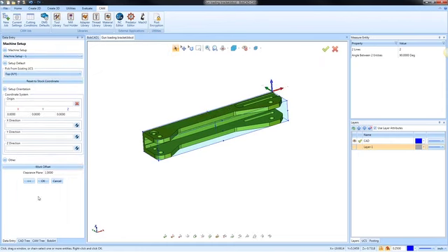Really, our next step here is to set our 0 position, okay, or our origin, as we call it: coordinate system, setup orientation, coordinate system, origin. This origin that we're going to pick here, this is your 0, your work offset, your touch off position. The position we pick here has to match the position we set up on the machine. Now, by default, it's picking up the world coordinate system. In my example, I'm just going to choose top center. Depending on your setup and your equipment and your fixturing, it could be anywhere. It just needs to match.